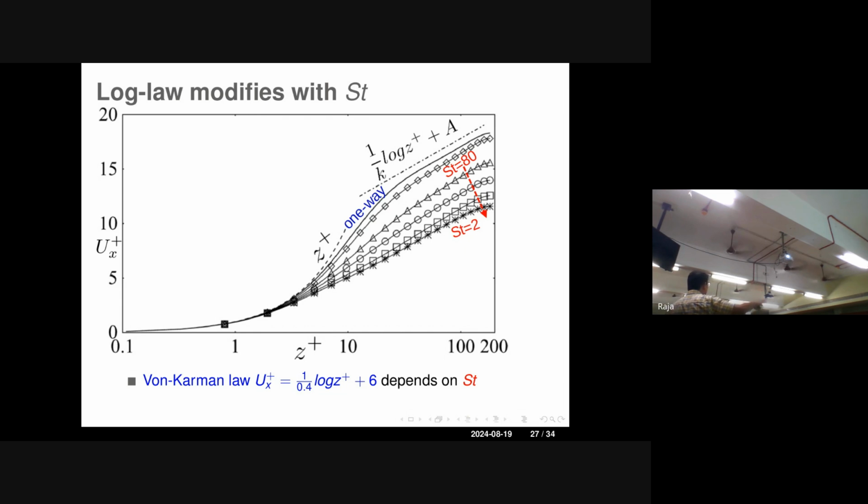So we always talk in terms of your particle time scale. In some sense, it comes via your settling velocity. The way one will pretend is, you have one particle suspended in water. It reaches one steady sinking velocity. That means I will be in a position to connect that if the particle is this, my gravity is so, and so on in a viscous medium. I can connect dp square, multiplied by the density, divided by the viscosity of the system, which gives you a time scale for that one particle.